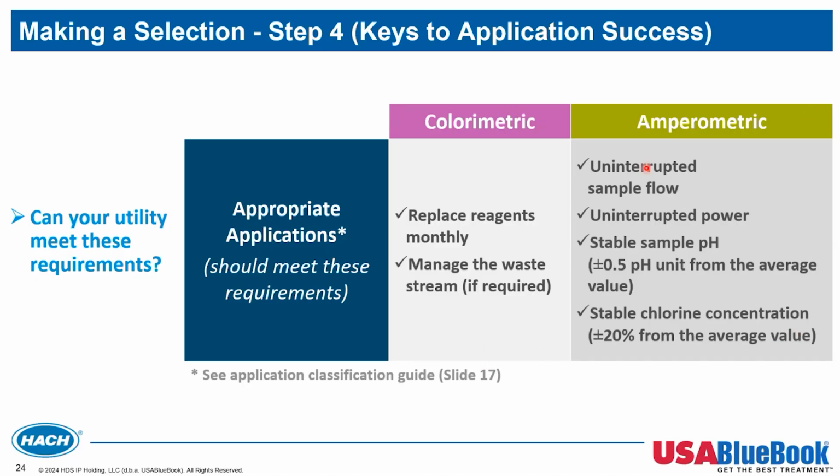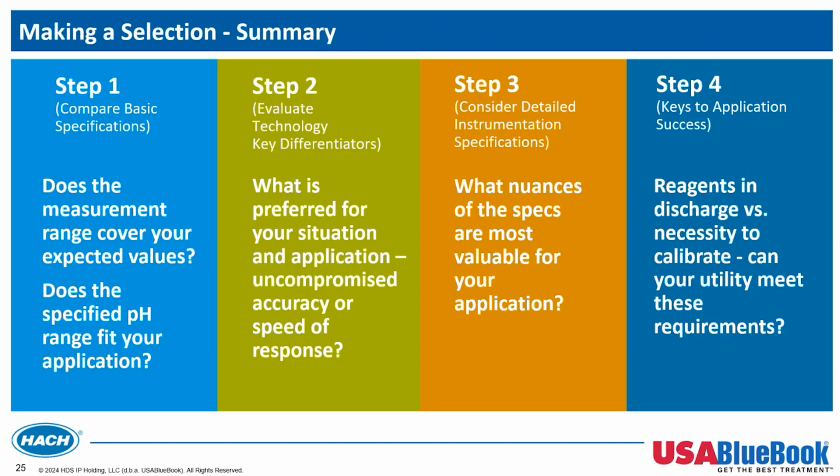With the Amperometric technology, do you have uninterrupted sample flow? Do you have uninterrupted power? Is your sample pH stable within half a unit roughly? Is your chlorine concentration stable roughly within plus or minus 20%? Those things are all important, and those are aspects of your application. Now, just to summarize the selection,